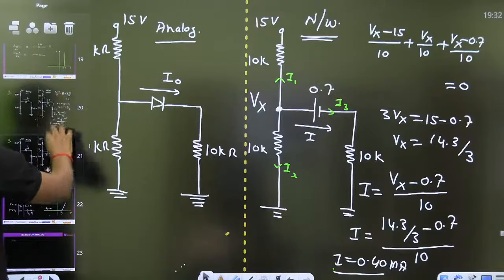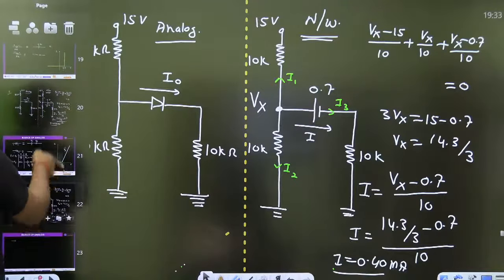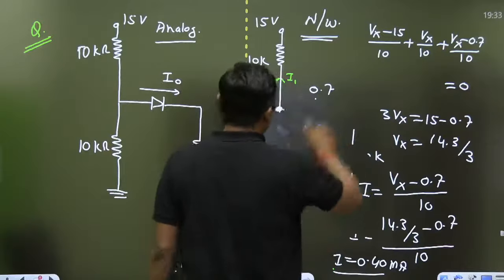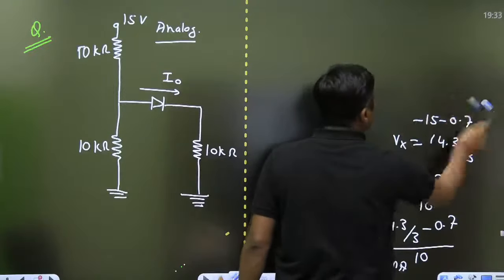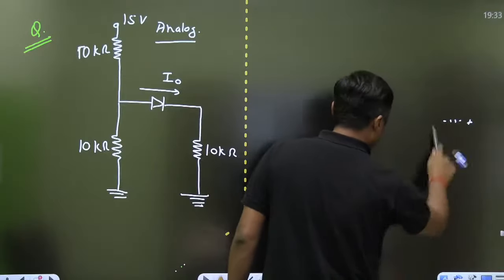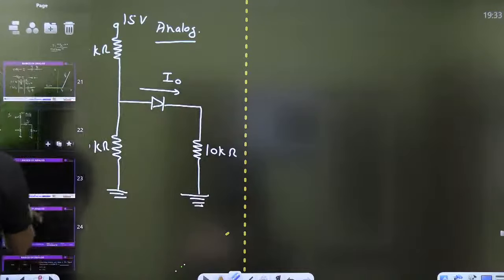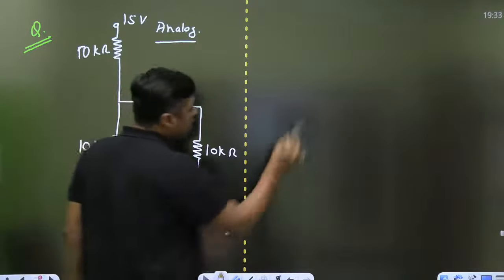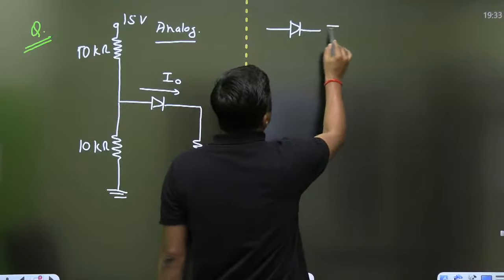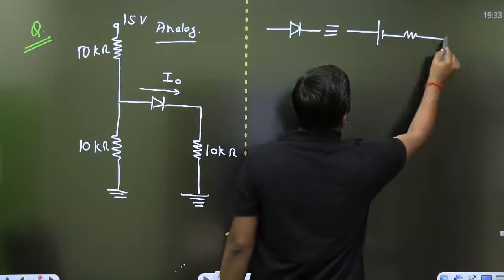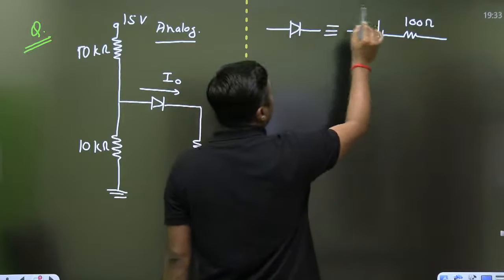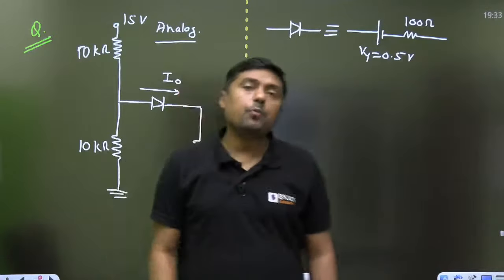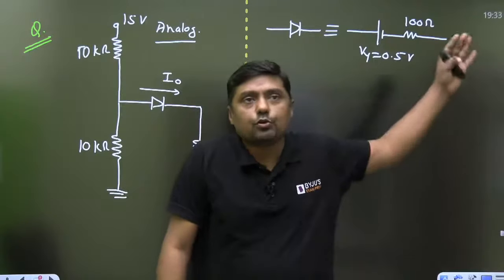Now you can compare, when we are considering the ideal condition, what will be the change, guys? Okay. Now focus on this. This time I want the right answer. Okay, what is given? For example, this question is given. This is the diode. This is the 100 ohm resistance, and the cut-in voltage is given as 0.5 volt. If it is mentioned in the question, it may be 0.5 volt, 0.6 volt, or 0.7 volt. Let me give you 0.5 volt for silicon.